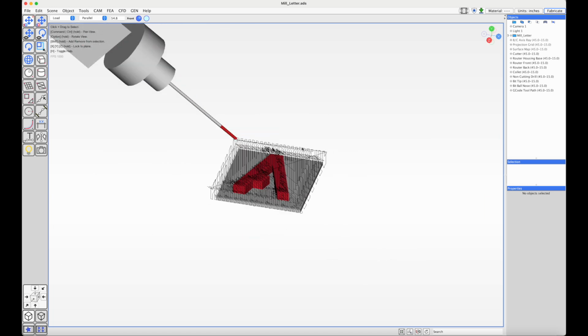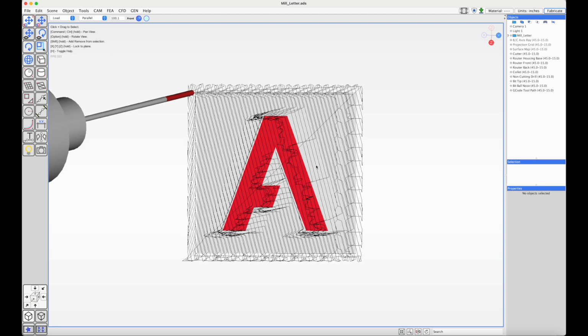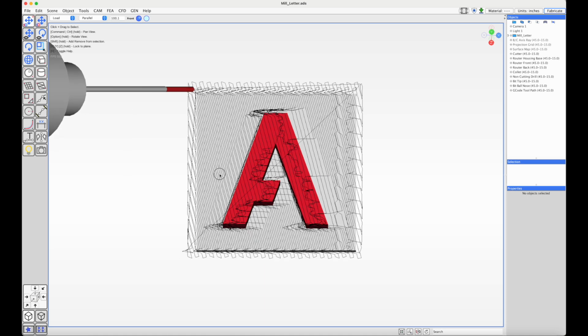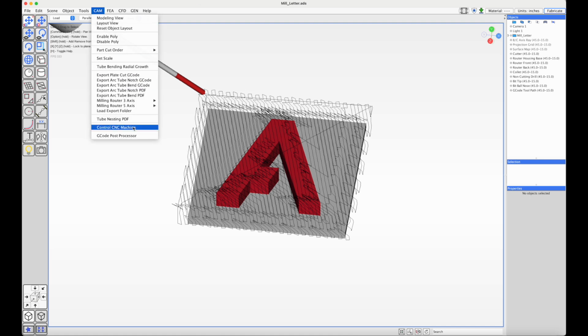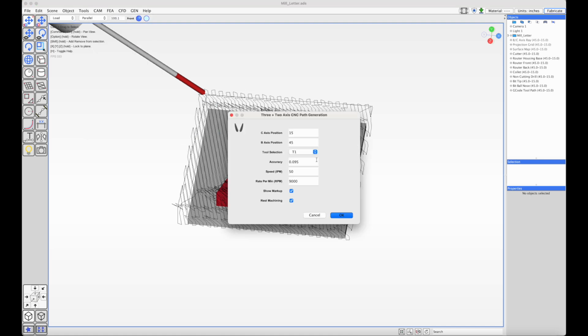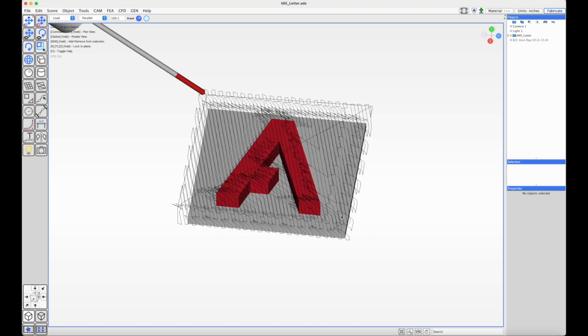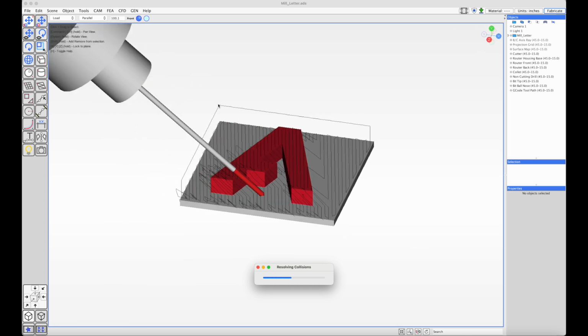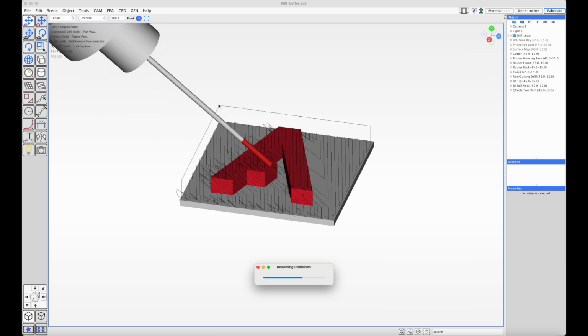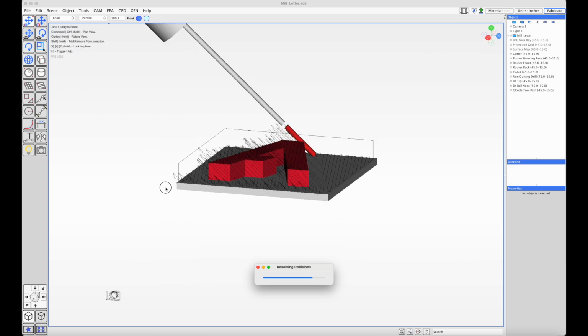The idea being that when running a roughing pass, we're going to run it as fast as we can, and the gantry and the drill bit can wobble slightly at high speeds, so we want to leave a little bit of padding. And then when we run a finishing pass, we're going to use the same orientation, the same tool, the same accuracy, and we will run that. So it starts in the X0 and Z0 coordinate so that you can align the block.